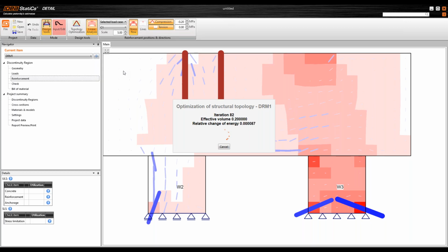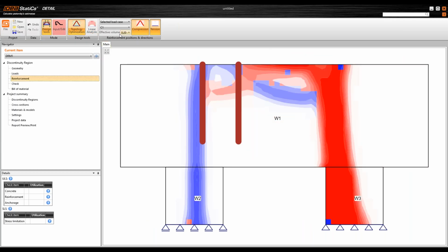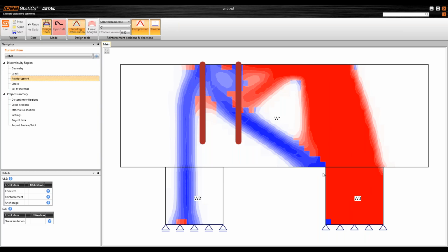It will remind you of something like a Strut&Tie, but generally it's not a Strut&Tie. But it will show you where the tensile areas are and the best way of putting the reinforcement. So this is very helpful for the details where you don't know how to reinforce it.